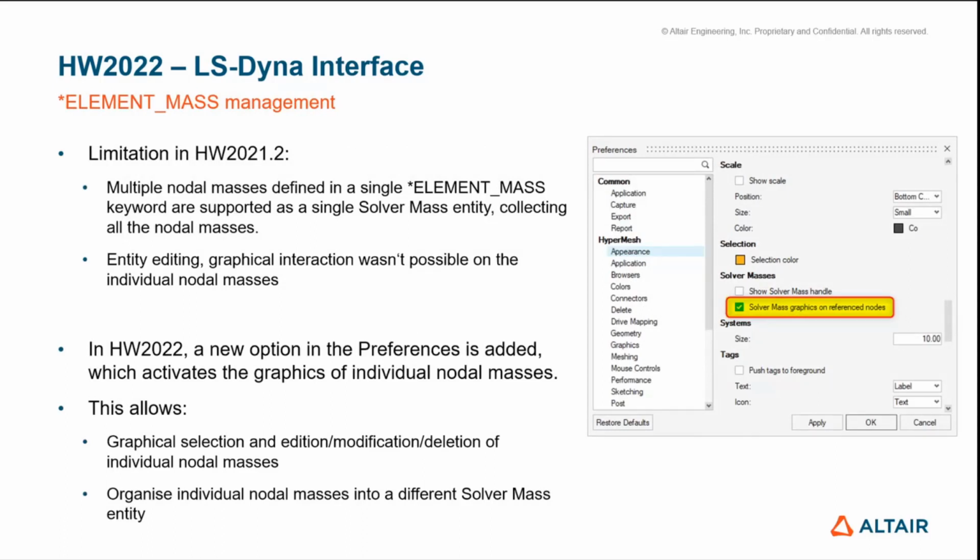Regarding an important update and enhancement on existing entities, for the element mass: as you may know, in the existing 2021.2 release, we have all the element mass keywords in LS-DYNA mapped inside the solver mass entity.